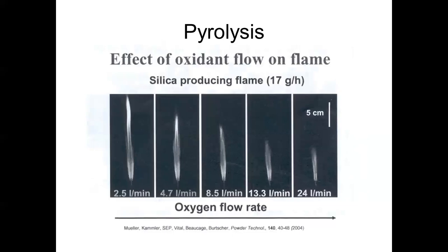I would think that the reaction would be greater and the flame would be hotter, but actually sometimes the oxygen itself would be in such a large amount that it would act as a diluent. So instead of making the process happen and being used as an oxidizer in the chemical process, it's going to act to prevent things from happening. It's actually going to act as a diluent because there's too much oxygen within the flame design, the burner design